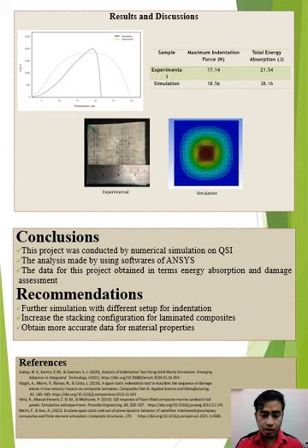Recommendation. There are 3 recommendations for this project. First, simulation with different setups for the indentation. We can use different velocity and different indenter tips. Second, increase the stacking configuration for laminated composites. And lastly, obtain more accurate data for material properties.